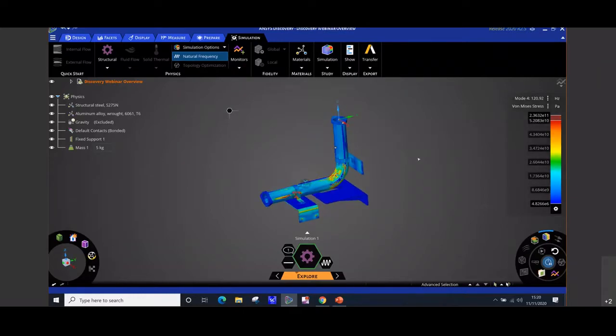So that is basically how easy it is to set up an initial simulation and actually get results very, very quickly. So this is in the explore stage. So that was just hopefully showing you the setup and actually solving a solution, a modal solution in this instance. So what I'm going to do is just pause that simulation and turn off the results, but you also do have different results, obviously for fluids, isosurfaces is quite useful, but for this, which is going to be looking at contours.